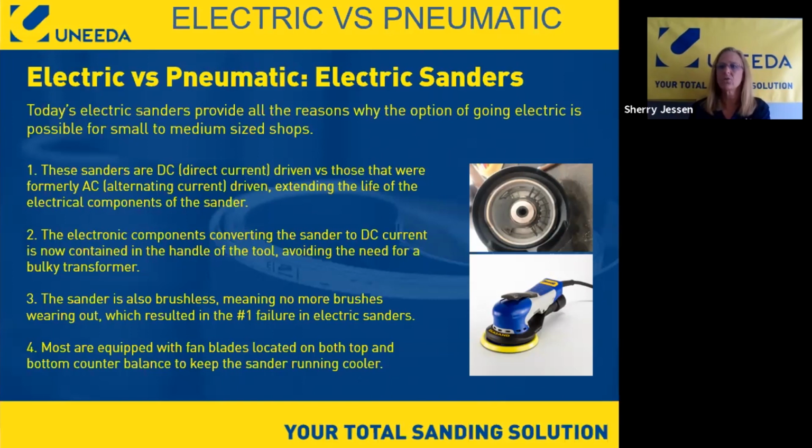It's a fan. So it's blowing the cooler air into that area to try to keep that center nut cooler. I've actually run a pneumatic sander without the fan blade, taken the backup pad off, and had somebody try to touch it. The center nut is hot. I mean, you can't touch it.